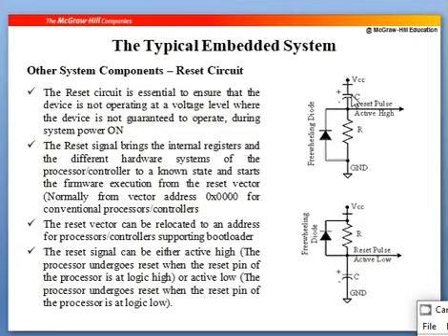As soon as the VCC voltage drops below a certain range, or think as if there is a connection breakage, so there is 0 volt or lower than 5 volt, then since you already have a voltage in this capacitor, the capacitor discharges. While it discharges, it follows this path. Initially there was a low signal.